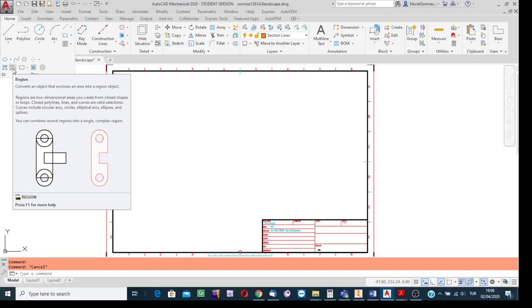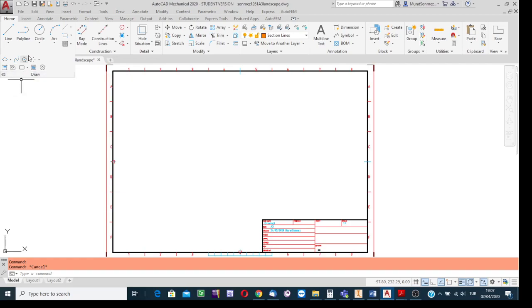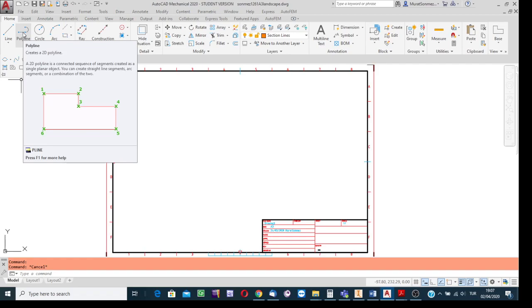Of course, if it is necessary to do such a thing, the surface bounded by the boundary lines will be indicated as a region for creating the solid model of the object or the solid model of a feature of the object, depending on the case. So instead of applying the region definition process, which takes a certain time in the order of 1-2 minutes, it is advantageous to just create the boundary lines using the polyline facility. It is recommended.